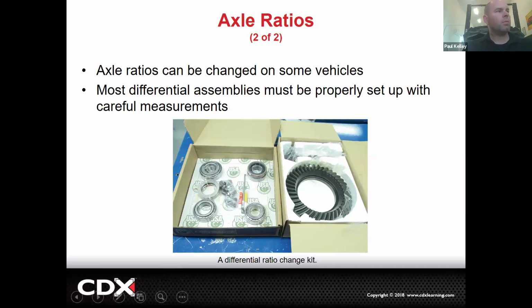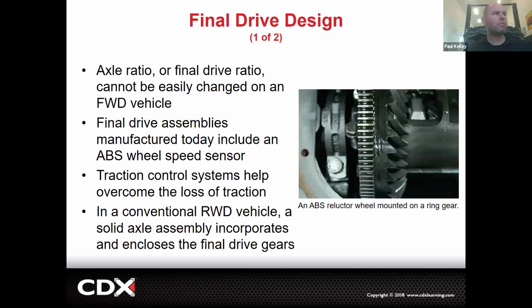Additionally, it comes with bearings. I mean, you can see this is not going to be a real expensive set, right? We've got a couple side bearings and a couple pinion bearings. Maybe it comes with a couple different shims because you may need to reshim it and adjust it. A lot of times it'll come with some marking compound and some Loctite. And pretty much that's your regear. Cool. It's a lot more complicated than that because you have to make sure that ring gear and that pinion are in perfect alignment. The orientation has to be perfect. That's the difficult part about doing differential work, and it requires quite a bit of special service tools. But that's the overall.